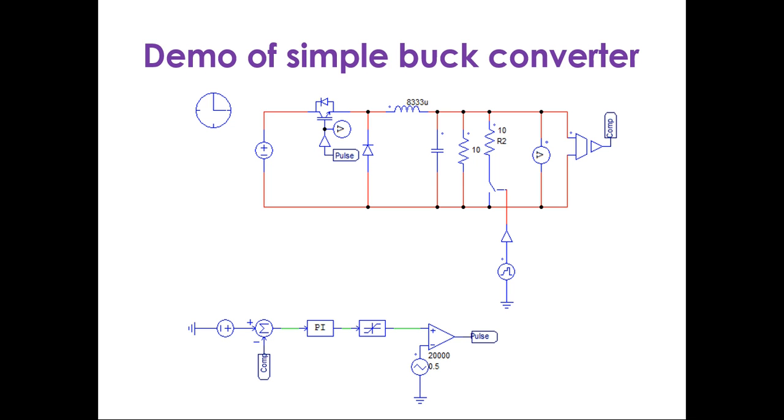Now I'll start a demo of the simple buck converter in the closed loop manner. We have designed the inductor and capacitor. Lots of online converters are available, and in this case, I have used the online buck converter, boost converter, and buck boost converter calculations, authored by Michael Green, published by Texas Instruments Incorporated.